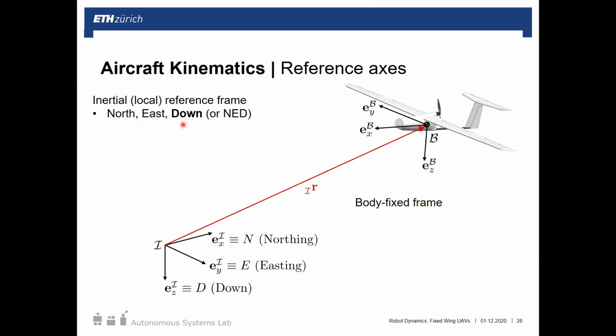So if you were still using cardinal coordinates here. So just remember, it's an aerospace convention, northeast down. So then that x-axis is the northing, y-axis the easting, and z-axis down. So then for the plane itself, you can remember this nicely by saying that x is always out the nose, y is out the right wing, and then z you can complete with the right-hand rule.